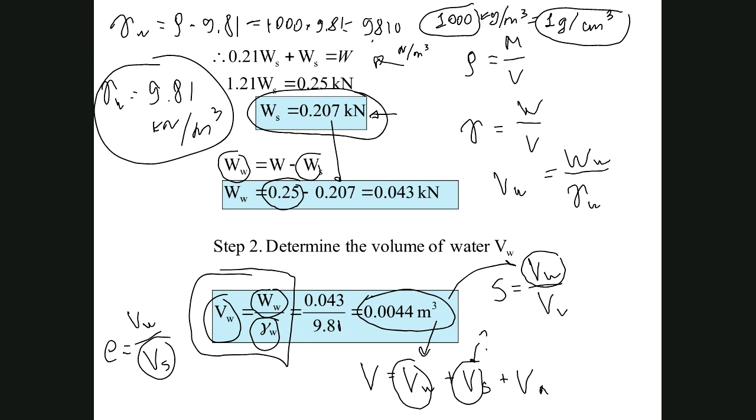Density of solids depends on the type of minerals in the soil. It can be quartz, calcite, or feldspar. So it always has a different density. So we know the weight, or mass of solids, and we just need to find the volume. To find the volume, I will show you there is another ratio that I explained to you. It's specific gravity.